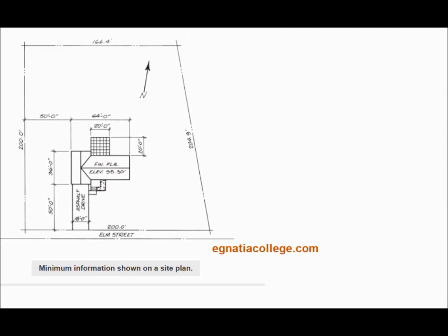Site plans. A site plan gives information about the site on which the building is to be constructed. The boundaries of the site, property lines, are shown. The property line is usually a heavy line with 1 or 2 short dashes between longer line segments. The lengths of the boundaries are noted next to the line symbol. Property descriptions are usually the result of a survey by a surveyor.